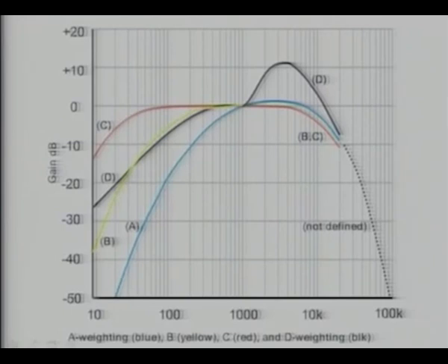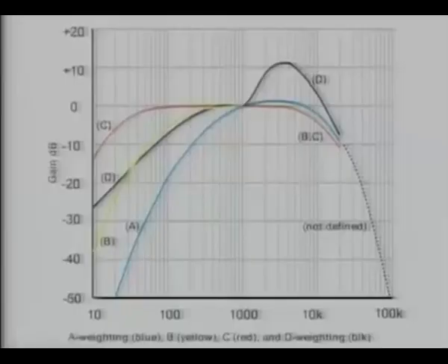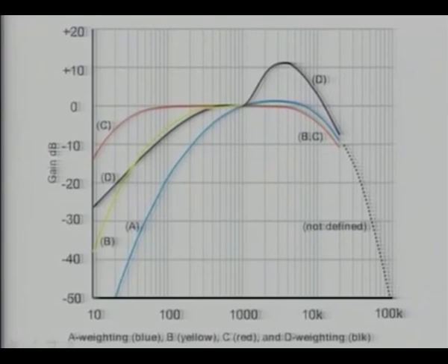But it's important to know that in industry, when you measure sound, people ask, what type of weighting level did you use? A, B, C. So you should be able to know what is being talked about. Now, the most prevalent weighting level in industry today is A. Because as you see, C, which is in red, is pretty much flat across a very wide spectrum, from let's say 30-40 hertz to 5,000 hertz.